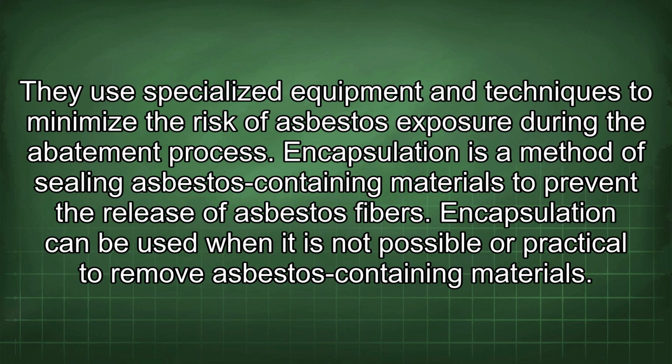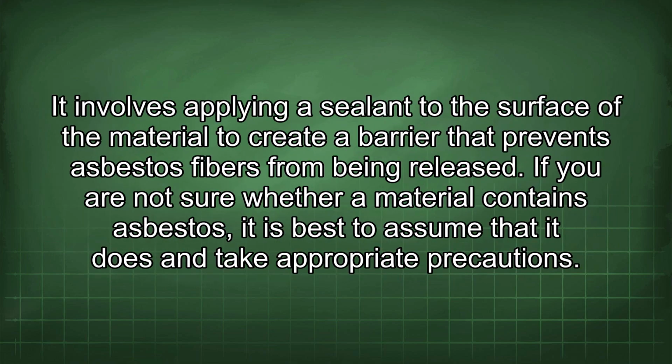Encapsulation is a method of sealing asbestos-containing materials to prevent the release of asbestos fibers. Encapsulation can be used when it is not possible or practical to remove asbestos-containing materials. It involves applying a sealant to the surface of the material to create a barrier that prevents asbestos fibers from being released.